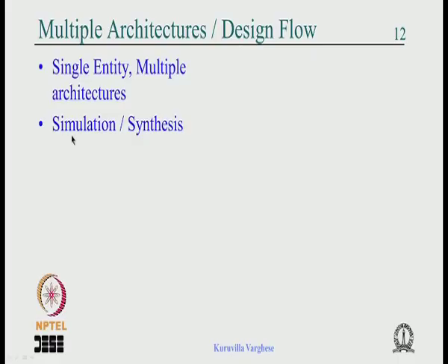So maybe you are developing a system and you want to quickly check whether the ideas are okay. You can write a quick code without thinking much about synthesis and make sure your idea is correct, and then you can work on how to write code which can be synthesized.